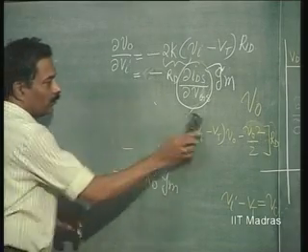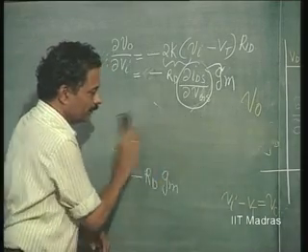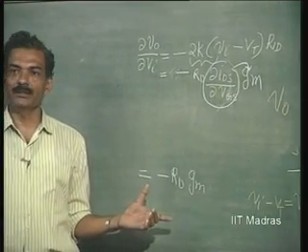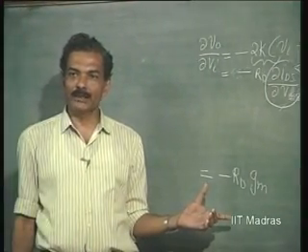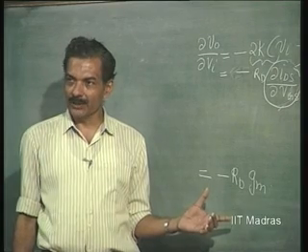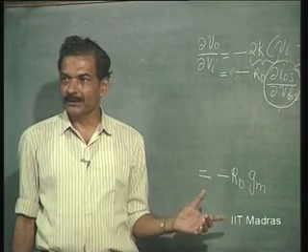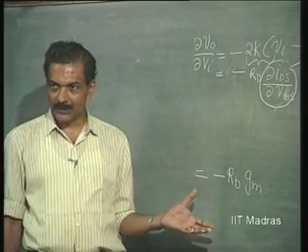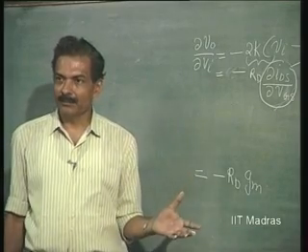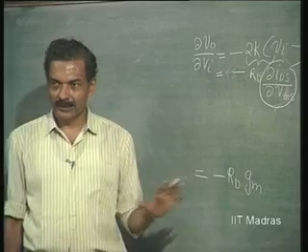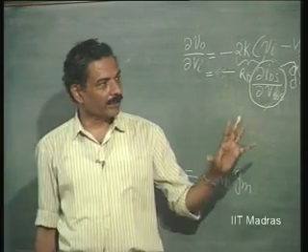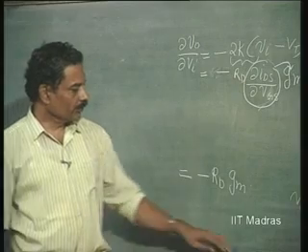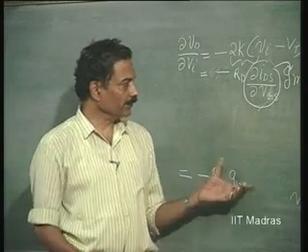So, please remember that the same expression has been obtained in the case of the bipolar junction transistor. There also the gain was minus GM into RC. In the case of FET also the gain is minus GM into RD, and therefore these are exactly identical in their definitions. Okay. So, you should therefore know how one should obtain GM.